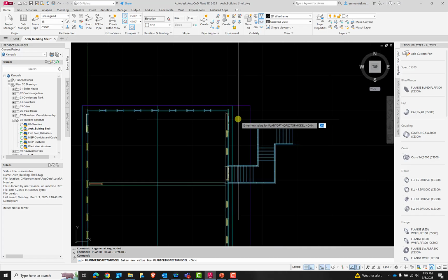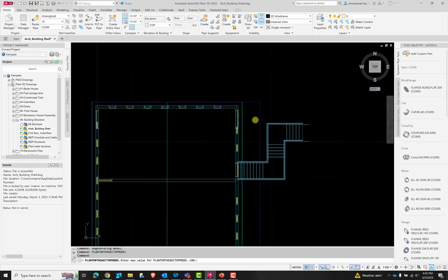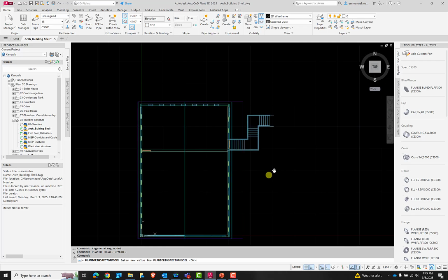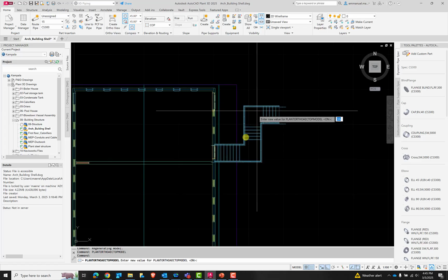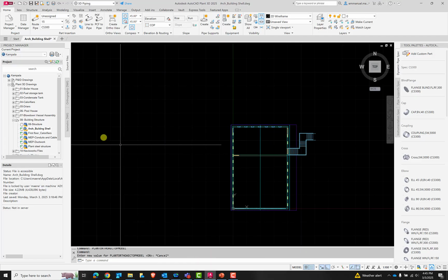For example, for this door, you'd want to see the representation of the door or the window at that top level, in addition to being able to see the stairs, because you wouldn't want to have something like this in your orthographic drawing. So you make sure that you have that one set to on.